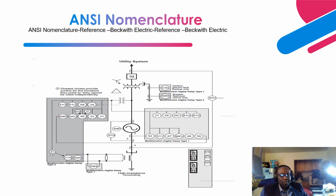Next is a typical setup of the generator protection elements for a typical power plant. As you can see over here, this is the connected utility system, so the AC grid is on this side. This is the unit breaker, and its ANSI nomenclature is 52. Anytime you use the word 52, we know you're talking about a breaker or a unit breaker.